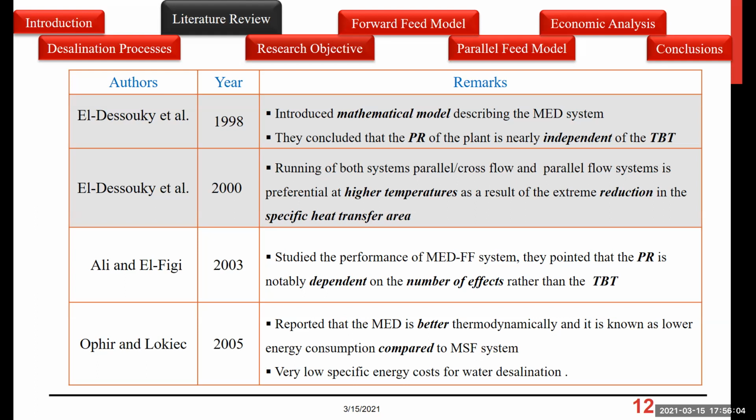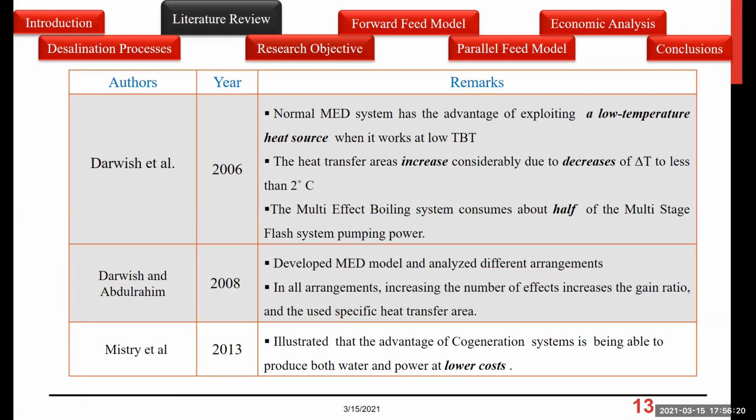Ophir and Lokiak, again, said that if we compare MED and MSF, then MED is going to be better thermodynamically because of the lower energy requirement compared with MSF. Darwish, he's actually the one that most of them have learned from, did some work here showing that the MED system has the advantage of operating at lower temperature, and that provides a way that we can operate it with low source energy or low grade energy.